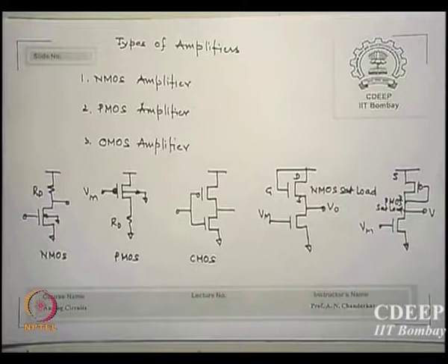So particularly in integrated circuits, we will normally never use RD, but for our circuit course, if I put RD, it does not really matter because it is external. I can go to the breadboard, take some 40k resistors from the rack and put them there, and we can test it. But in real life, when it goes to chip, we never put any resistances on chip any day unless it is necessary, in the case of RF circuits.